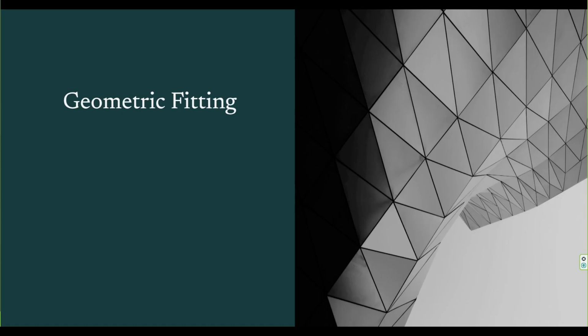And the last use of least squares adjustment can be described as geometric fitting. Let's imagine that we measure multiple points on a wall and we know the coordinates of these points, and we would like to approximate that wall somehow by fitting a plane. By fitting that plane, we will see which points are lying close to this average plane and which points are outliers.